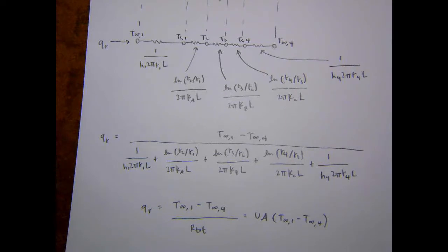Either way, you know your boundary conditions, and you can apply those, calculate the particular solution for the temperature distribution, take the derivative, calculate the heat transfer rate using Fourier's law, which is for conduction. But we know that heat transfer rate is also going to be the rate via convection because all these assumptions apply, and therefore the heat transfer rate is the same through all the materials, including via convection out into the fluids.